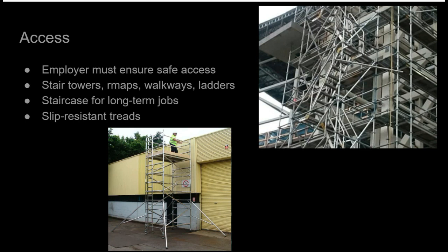Employers must ensure safe access to scaffolds through stair towers, ramps, walkways, or ladders. Staircases may be used for long-term jobs. Slip-resistant treads help protect against falls.